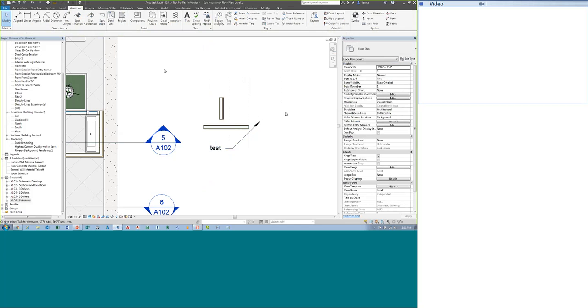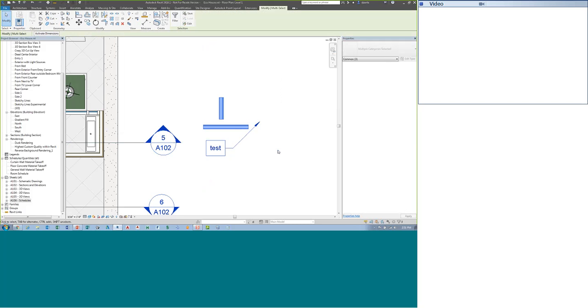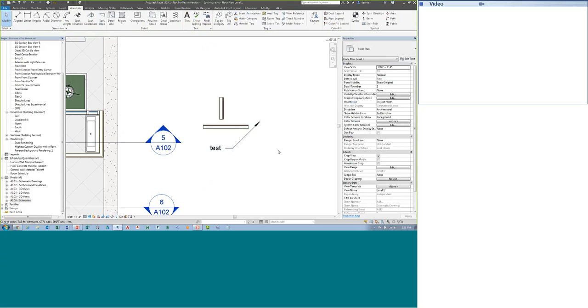If you do the window crossing from left to right, the box is a solid box, which means the entities have to be fully contained in order to be selected. Very similar to AutoCAD. However, AutoCAD also colors the boxes different colors, which is a plus because it's easy to see. And AutoCAD has a lassoing selection feature where Revit does not.